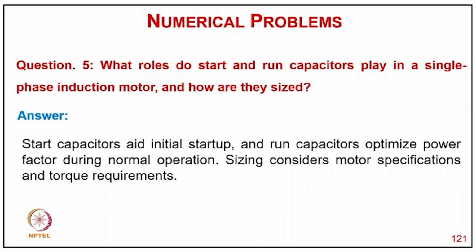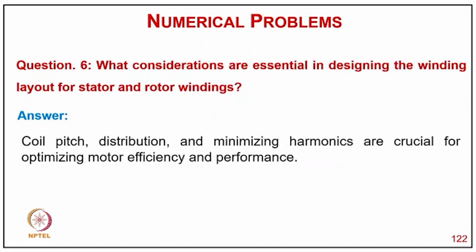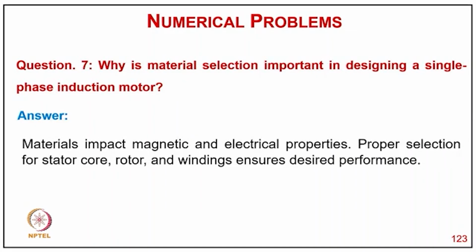So start capacitors aid initial startup, and run capacitors optimize the power factor during normal operation. Sizing should consider motor specification and torque requirement. What considerations are essential in designing the winding layout of a stator and rotor? Coil pitch, distribution, and minimizing the harmonics are crucial for optimizing the motor efficiency and performance.